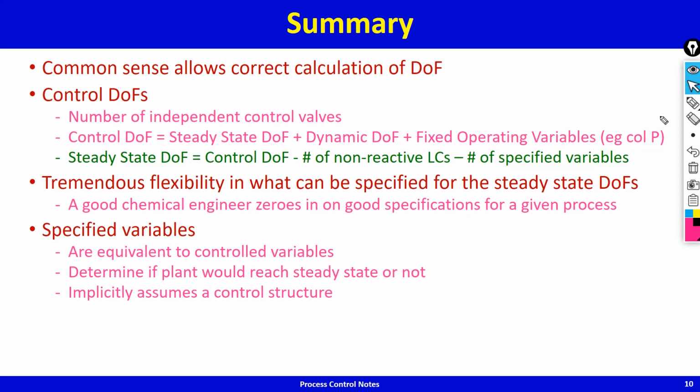The drifting stoichiometric imbalance, the drifting recycle inventory of the excess component in that toy process example, that's a subtle thing, and most people don't understand that subtle thing. And so you will have that drifting inventory if you don't install a controller that ensures stoichiometric feed balance based on feedback.